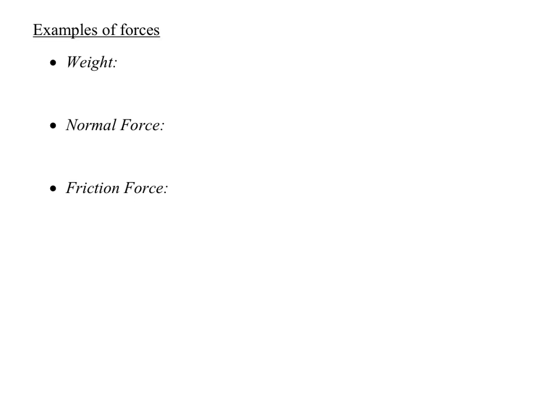Yeah, I mean, think about it, guys. Look, if the wind is pushing here, it doesn't have much of an effect. But if it's pushing here, this is the lever arm, the length of the building, or the height. So the taller the building, the more moment from wind occurs, or the more torque on the building. So it's going to sway naturally.